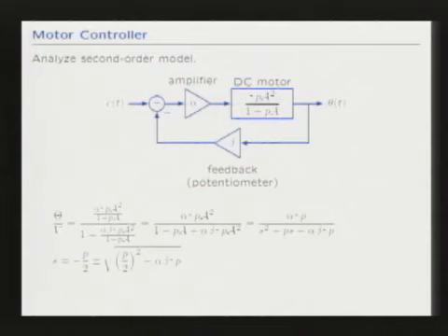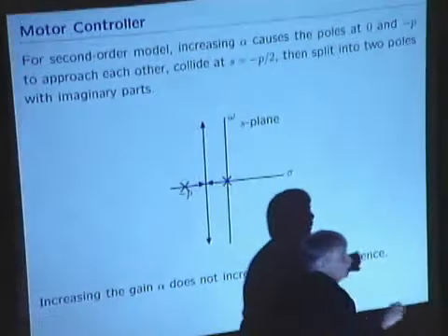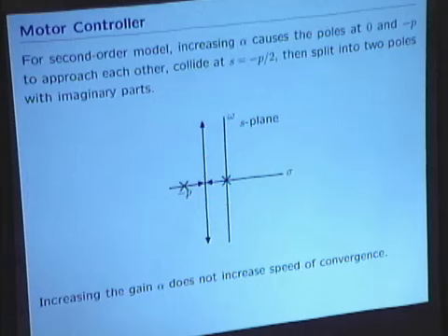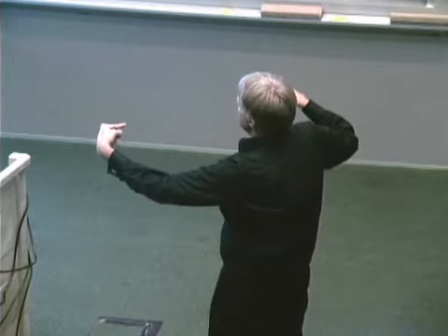That prediction is shown here, right? That's just thinking about system functions, saying that I've got two poles, figuring out where the poles are, figuring out what the time domain response is, integrating it to turn it into a step response, and you get a response. The point is that the new model looks like two poles, and when you analyze the root locus, those poles move when you change the feedback. So as I change the feedback number beta, as beta goes from 0 to big, the poles go toward each other and then split off.